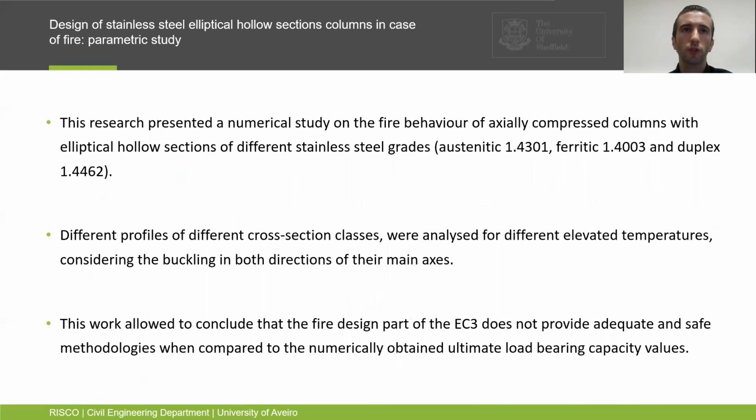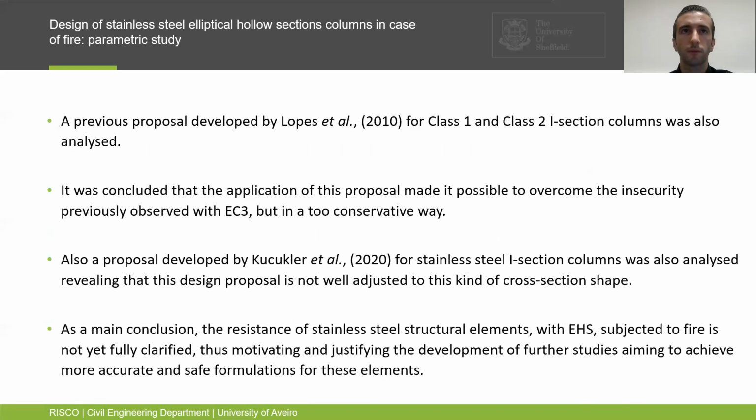From the main conclusions, this research presented a numerical study on the fire behavior of axially compressed columns with elliptical hollow sections of different stainless steel grades, considering profiles of different cross-section classes, analyzed for different elevated temperatures, considering the buckling in both directions of their main axes, concluding that the fire design part of Eurocode 3 does not provide adequate and safe methodologies.